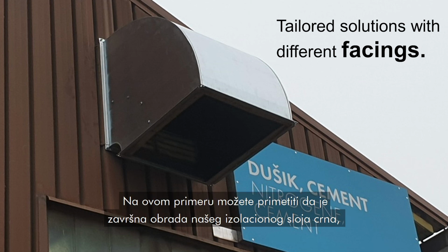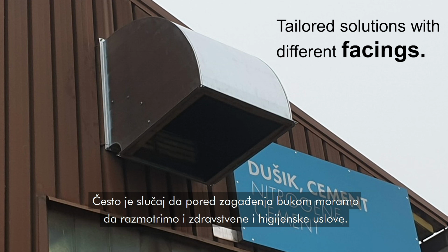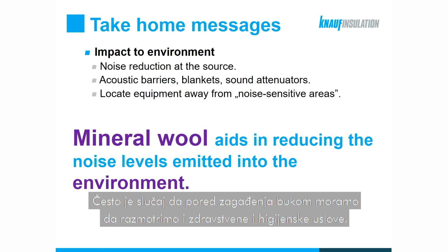In this particular example, you can notice that the finishing of the insulating layer is black. That's because of the facing applied to the insulation. This particular facing has been applied to prevent migration of fibers due to the airflow. So it's often the case that apart from noise pollution, we need to consider health or hygienic requirements too.